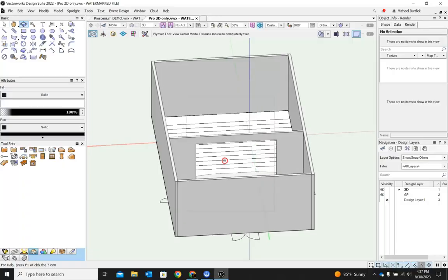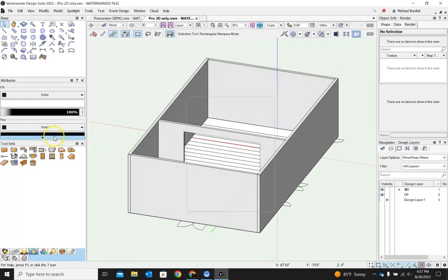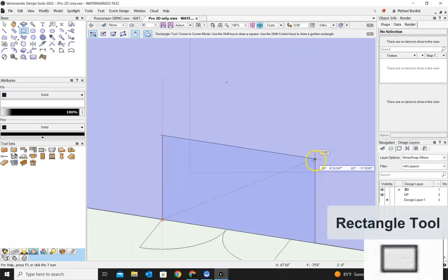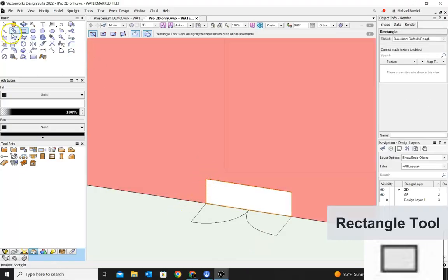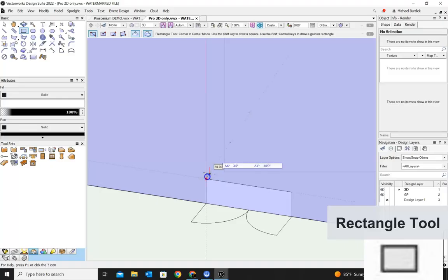We could do doors kind of the old school way as well if we wanted to. But the other way to do something like that would be to come in here and actually draw on the surface. So we know the stage comes up to 3 foot. And we know that this door is 10 foot wide. So I go 3 foot, tab, -10. So that's where the stage is. Hit escape, and then I would draw this, which is our -10 by 9 foot.